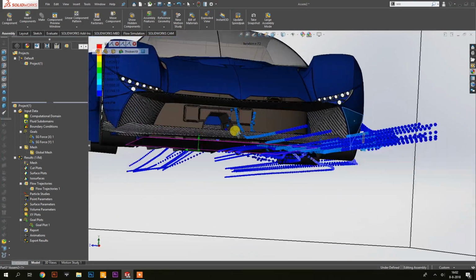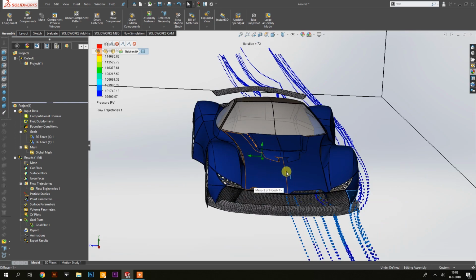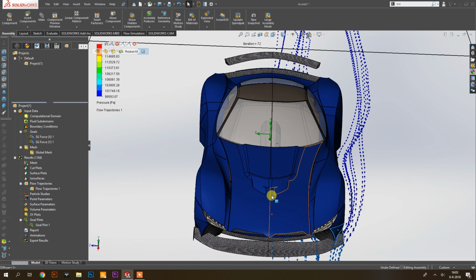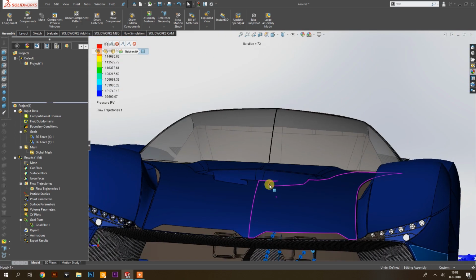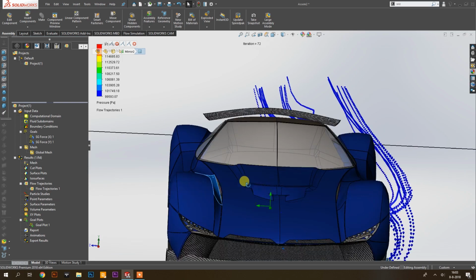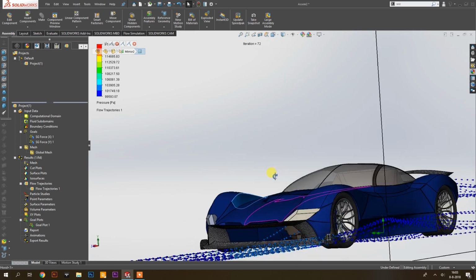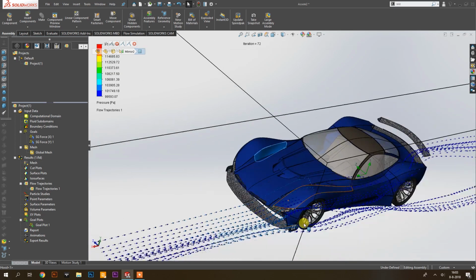And I think a lot of the lift coming from the car is because this big gaping hole is here without any of the air exiting to the ports where it's meant to exit. So a lot of the high pressure is building up underneath the hood, and it's dragging the car upward, I guess. So hopefully when I get to make the fence, that will redirect all of the air that is coming in here towards these fences to go out of the hood in different sections. Usually the downforce will increase again and things of that nature.